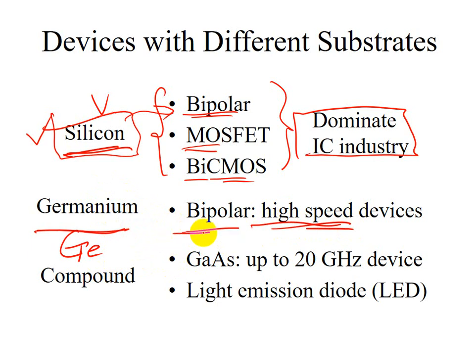and using bipolar junction transistor. It's fast, but you can create a lot of heat. So in general, for bipolar junction transistor, you're going to have a large heat sink. You have a large plate of heat sink on the back of the IC to dissipate the heat generated for the power device.